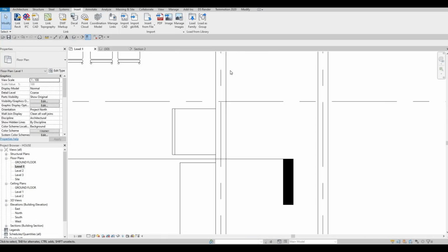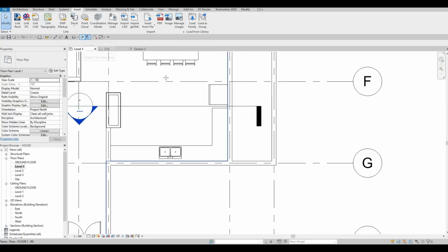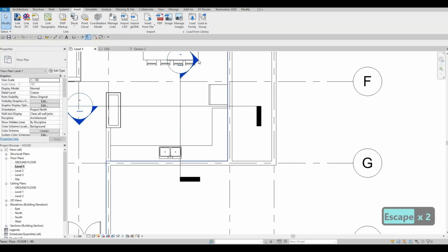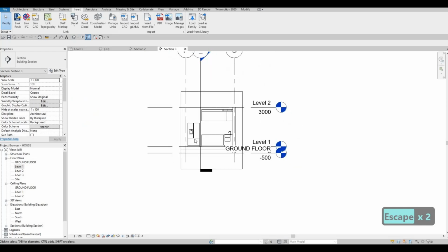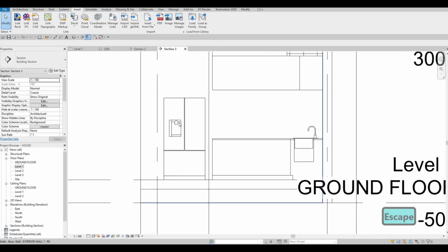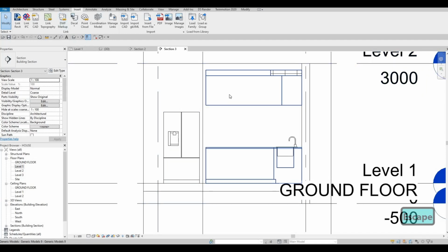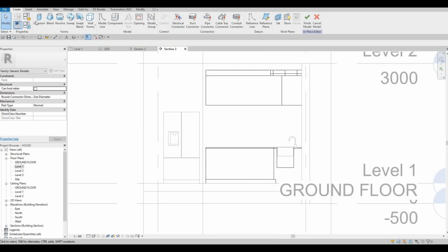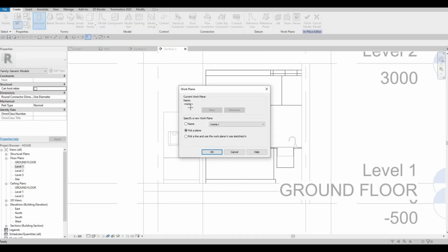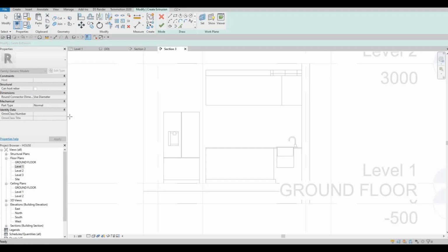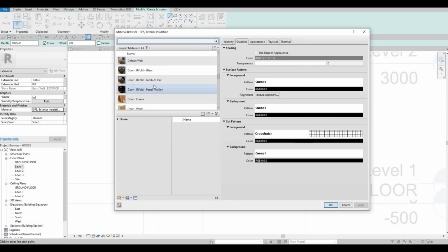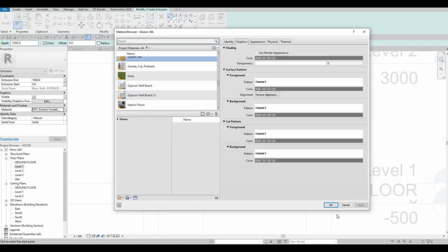So the good thing now is to add another section so that it's now facing on this side. So let's create that, and then now we could create our casing first. I'm gonna use this one, in place, edit that, extrusion, pick a plane, and then we're gonna select this wall, and we're going to select the same material that we have right there.